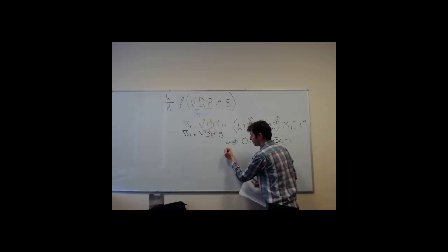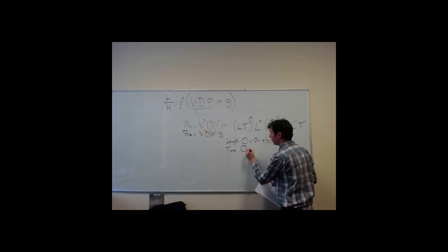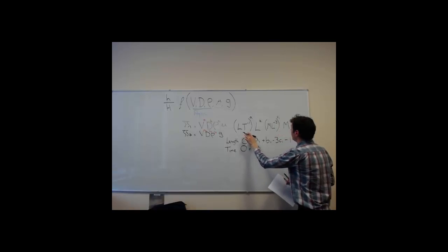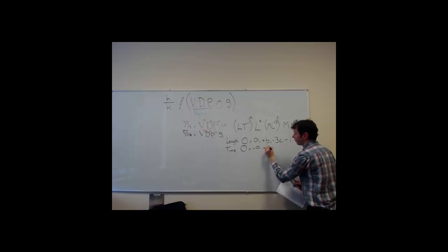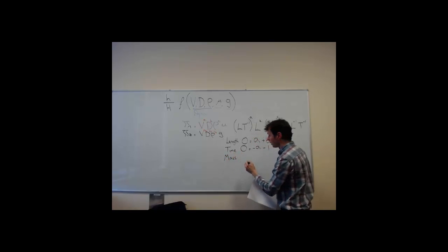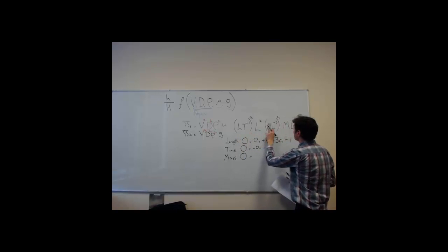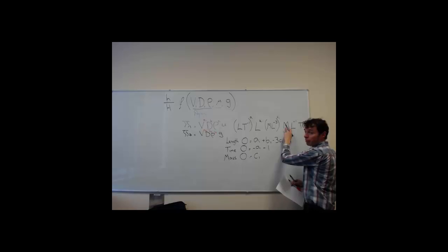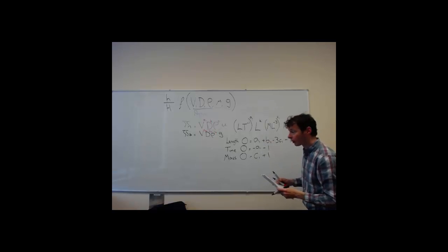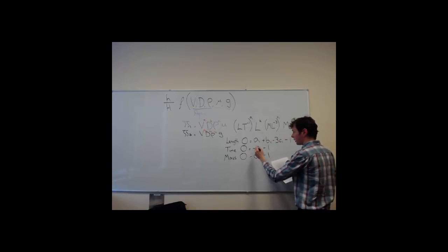So do the same for time. Again, the exponent of time, or the power we raise it to, is 0. So we have minus 1 here, so minus a1, and any more t's, 1 at the very end, minus 1. And finally for mass. Again, usually the length terms are quite numerous, so it makes more sense to solve for mass and time first. So 0 equals 1 there, so C1, and then an M here, plus 1. Okay, and now we can solve for A1, B1, and C1. If we solve those, we end up with each one equal to minus 1.